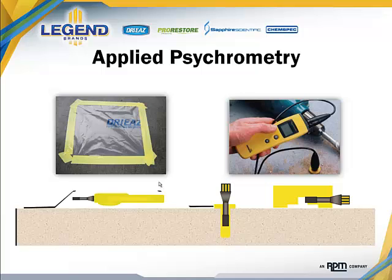Just several examples here of some creative hygrometer use. I'll run through each one of these and describe what's being done. Here we have a hygrometer that is underneath a plastic sheet. And there are lots of varieties of plastic that would work for this. Any standard low permeance or non-permeable plastic sheeting will work. The only requirement that I'd give you is make sure that the plastic sheeting is clear, because we're going to put a hygrometer underneath that plastic sheet, and we want to be able to see the display.